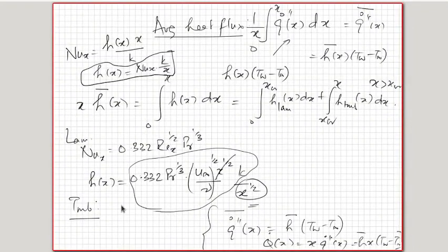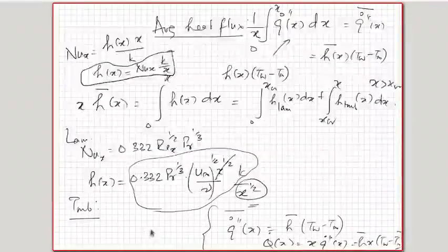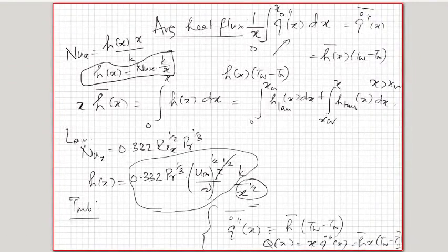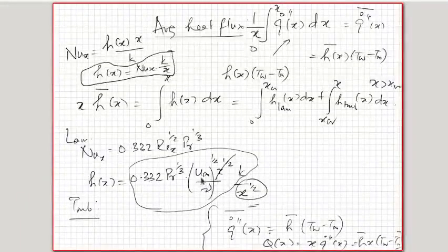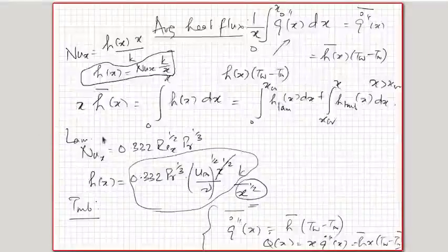So it's a straightforward thing, but I thought that it's important to explicitly state all of this in order to avoid any casual errors resulting out of directly trying to integrate Cf on one side and Nu on the other side. Cf integration comes out to be correct, whereas the Nu integration comes out to be wrong because there is a dependence of 1 by x between h and Nu. So that needs to be taken into account. Okay. So I'll stop this lecture here. These are the miscellaneous points that I wanted to convey to the class.